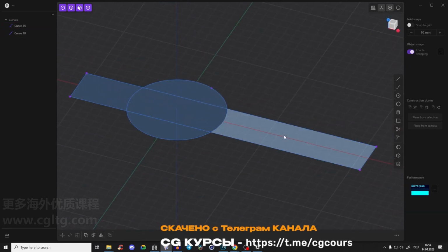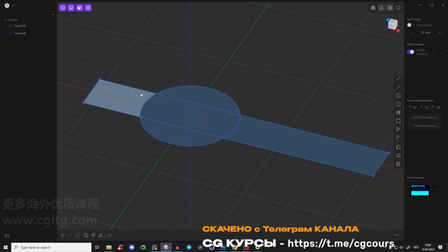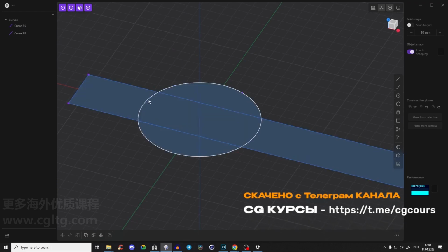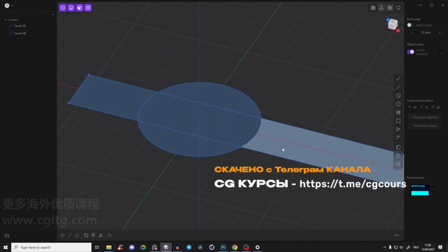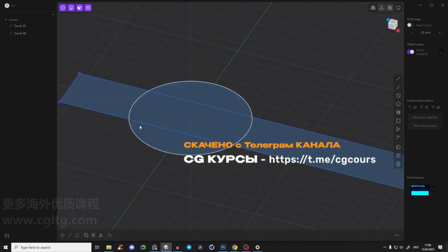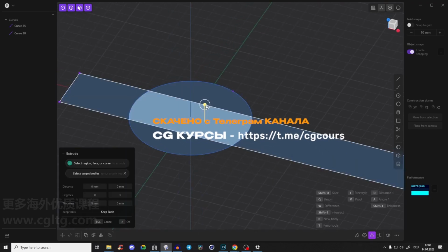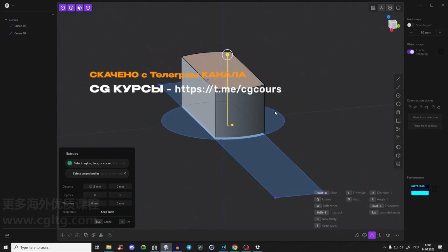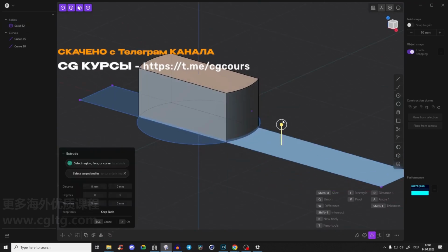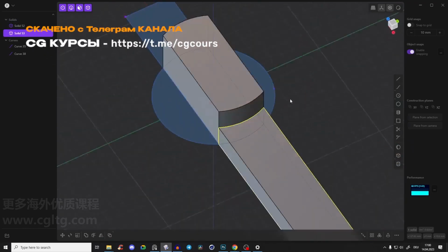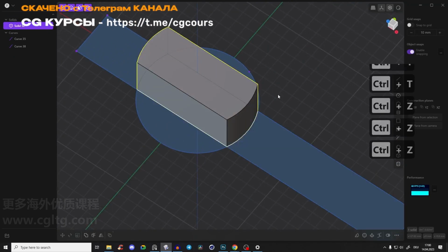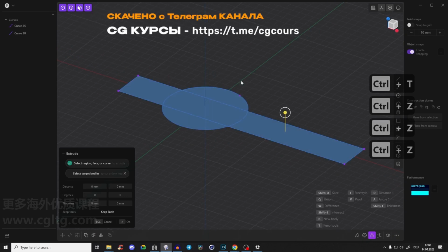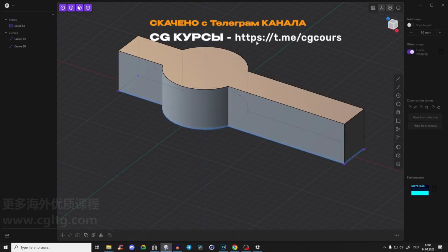And you see already that everything is blue. So what we could do now is, we also have these edges here. You see we can select only one part of this light blue part and select it with face mode or all modes selected and just drag it out. So we can just extrude it here, or we can extrude it here like a little part. So this is very cool. And if we want to select this whole piece, no problem. Then we can just select all of those areas and just drag it out. Perfect.